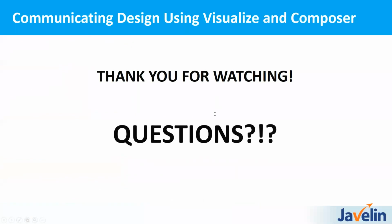So I do have a question saying Visualize cannot do animation videos unless you have the professional versions, where PhotoView 360 can do videos, and that is absolutely true. So animations are done in PhotoView 360 Pro, whereas you can do the motion studies inside of SolidWorks and you can render them out in PhotoView 360. You'll be required to have SolidWorks Professional or higher, but you won't need any extra licensing for that. You will be able to render out videos. And of course, as I mentioned with the network rendering, you can network render videos as of SolidWorks 2017.